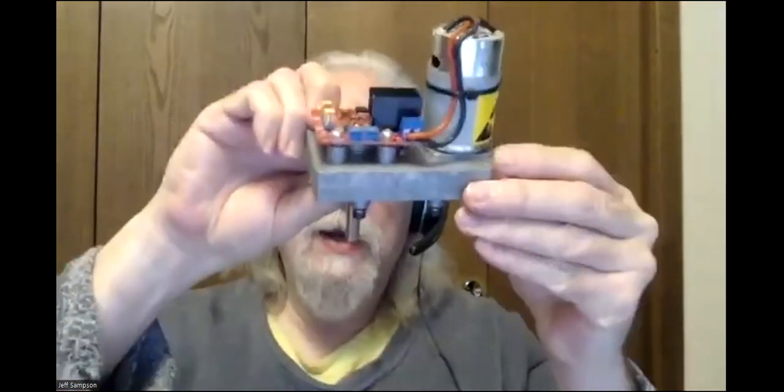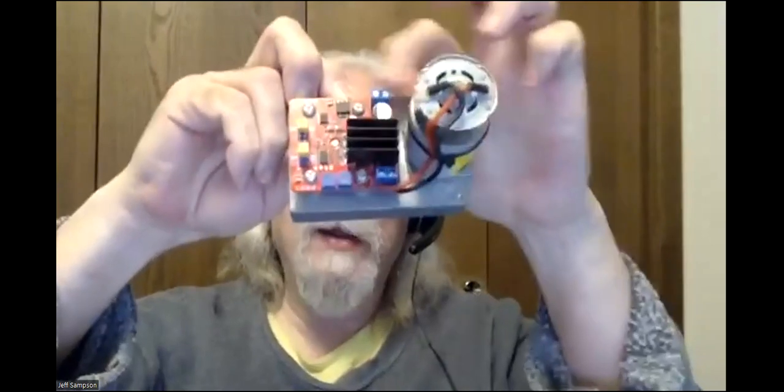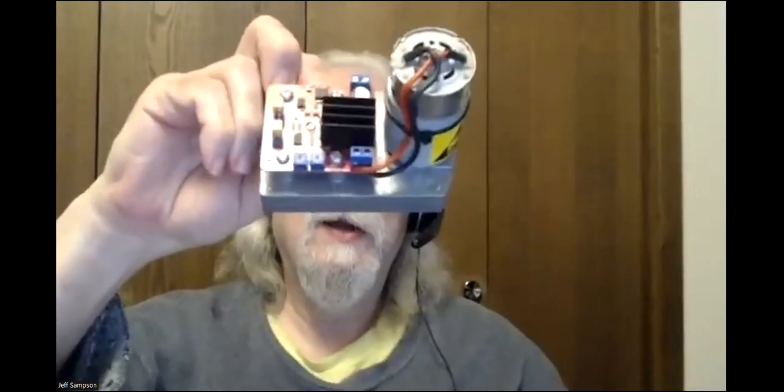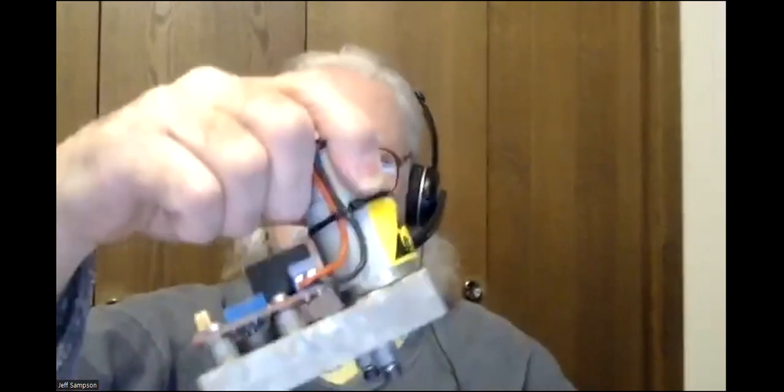This one doesn't have the wire soldered on the pot yet, but if I solder that wire on and connect this to an Arduino Nano, the Nano can generate the PWM to tell it to move and then measure the analog coming back. I should be able to plug in a servo and write some software that goes through some pattern and tracks it to see, is it following like it's supposed to? And then I could try it on this one.